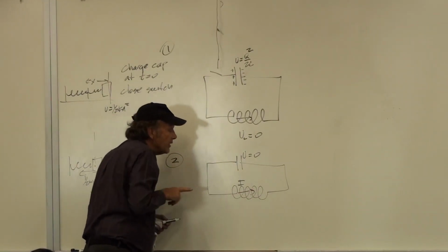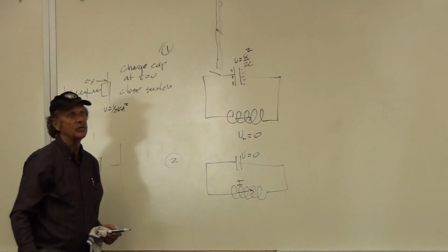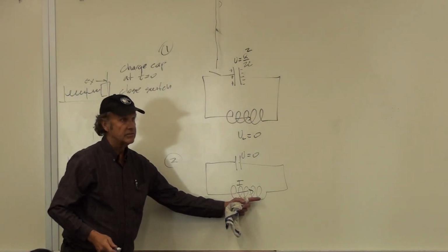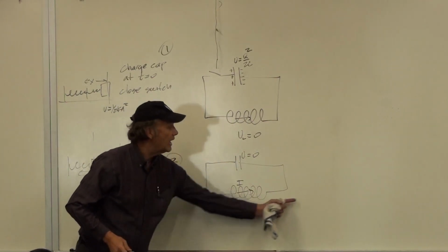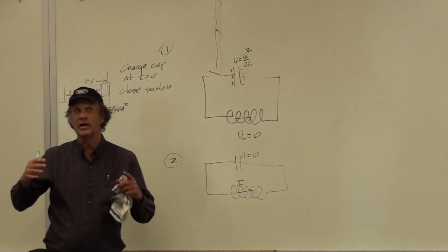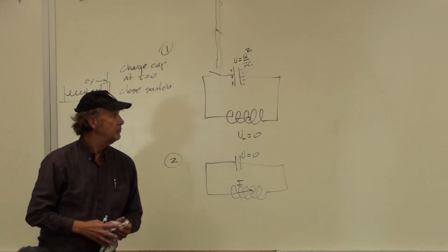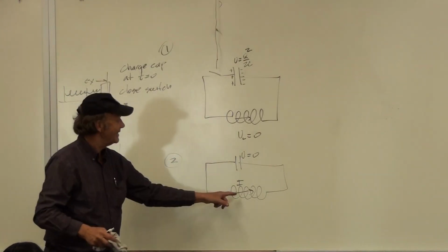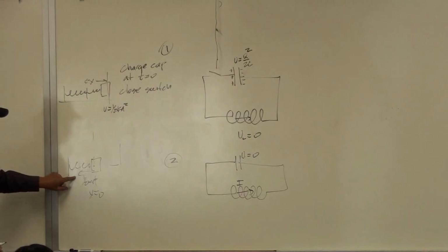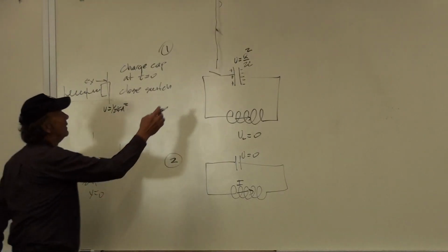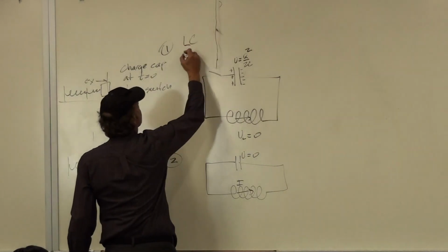The back currents are going to help drive it in the same direction, because that's the direction of decreasing current. So the eddy currents switch direction now, and now they're moving to drive this thing through that point. So it doesn't just instantly cause the current to drop to zero, but rather, it's like taking potential energy, turning it into kinetic energy, just like here. This is the electromechanical analog for what we call an LC circuit.